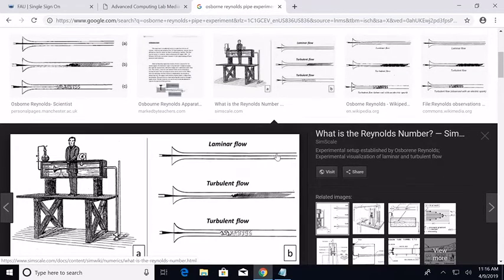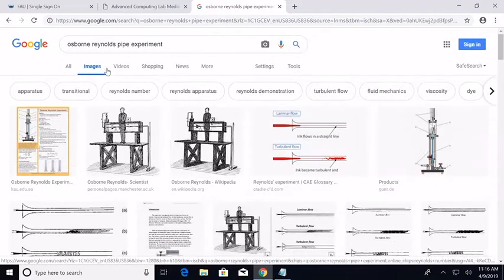Right? Do you believe this? Why do you believe this? Why would you believe that it's laminar? You're injecting one fluid into another. It's moving really slow. Yeah, if it's moving really slow, any disturbance that happens at the interface quickly dies out because the viscosity is so high. Okay, and this actually happens.